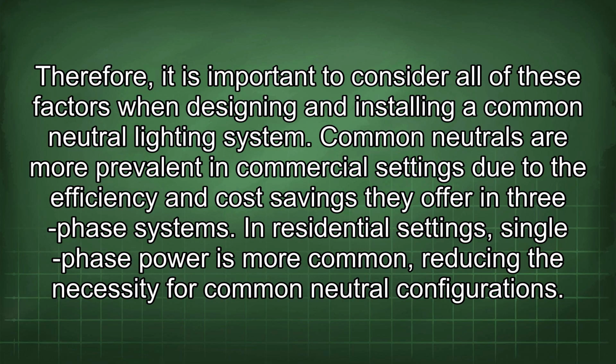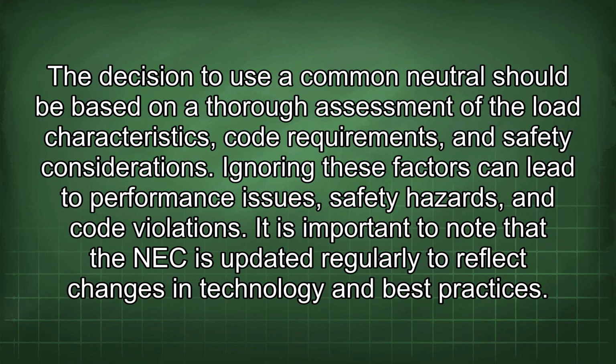Common neutrals are more prevalent in commercial settings due to the efficiency and cost savings they offer in three-phase systems. In residential settings, single-phase power is more common, reducing the necessity for common neutral configurations. The decision to use a common neutral should be based on a thorough assessment of the load characteristics, code requirements, and safety considerations. Ignoring these factors can lead to performance issues, safety hazards, and code violations.